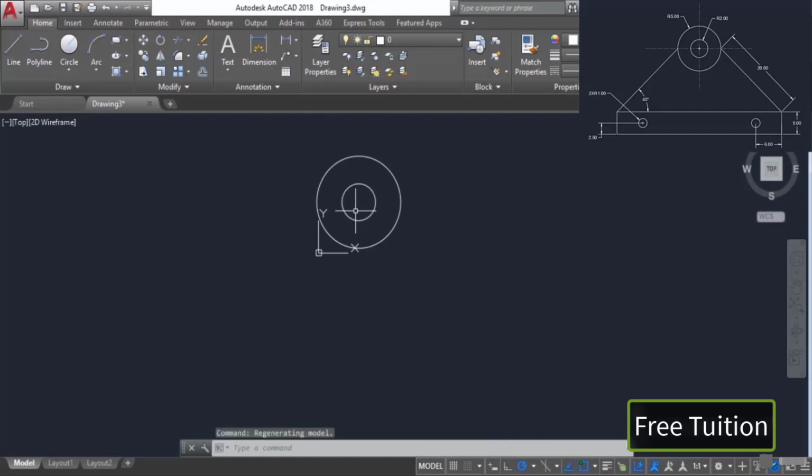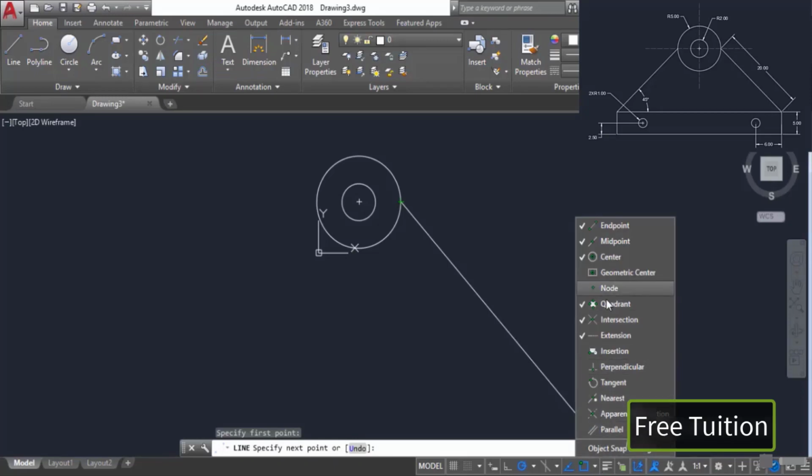Now let's start with the line tool. So I'll click on line and now click at this quadrant, and if the quadrant is not visible, then you can click on this object snap option, and right beside that there is this small arrow. Just click on it and turn on this quadrant. Although this is a tool which we'll learn later on, a little bit of knowledge of this tool is very helpful in making these kinds of drawings. So you can turn on quadrant to see that point.